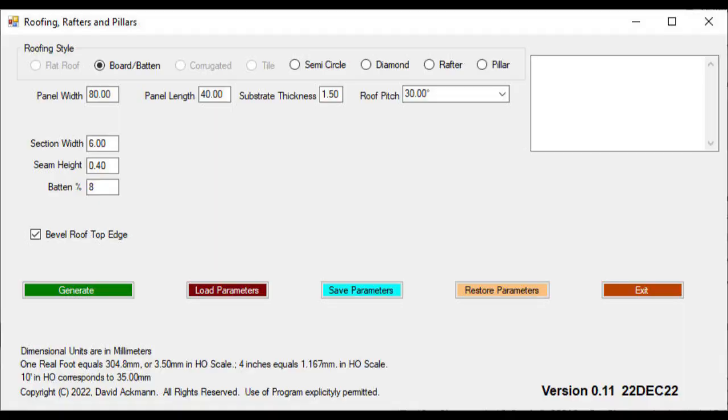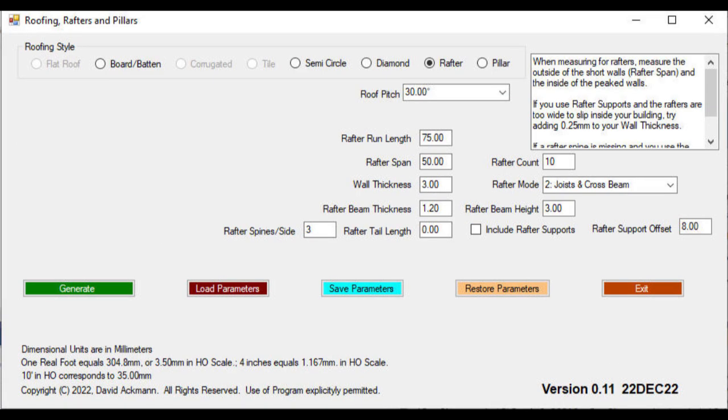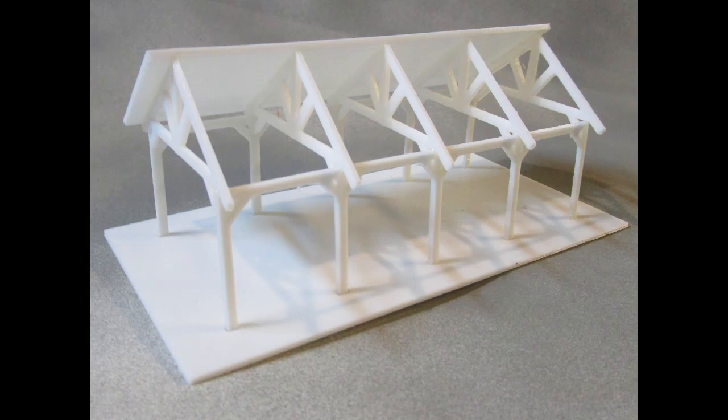The existing roofing generator allows for the specification of the building length, span, and pitch, so I used these to design a basic truss. The number of trusses can be specified and the number of stringers connecting each truss as well. The sizes of the truss members is also under your control. If you want vertical corbels to attach to the wall, well, that functionality is available too.